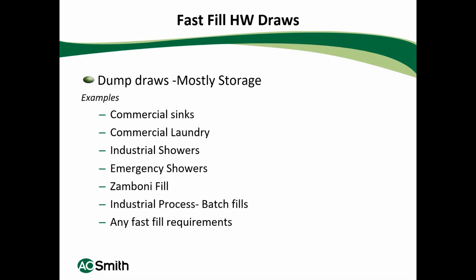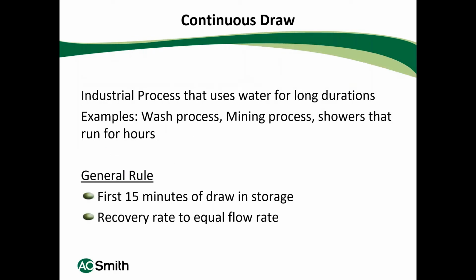And then emergency showers, that's a commonly asked question, so I'm going to run through an application of that. Zamboni fills are also a high dump load, so they usually are always in storage. And so is any industrial process where they're filling a tank for whatever, making cosmetics or whatever. And of course, any fast fill requirements, where they want to transfer a whole lot of water very quickly, you really want to put that in storage.